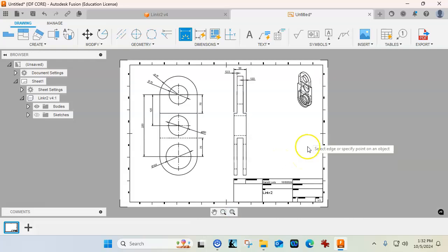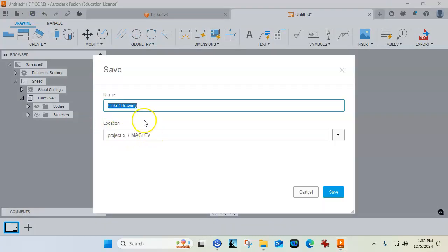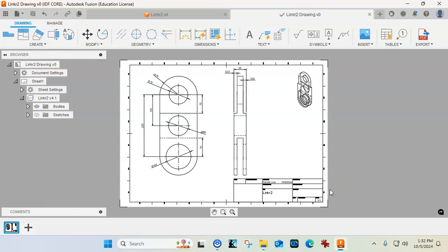F6 to fit it to the sheet, and then we would save this, and now we have a working document we print to. If I created my own template, I prefer to go across the bottom, clean that up. Not exactly sure what size I picked either, so this looks like a pretty good size sheet anyway. So we'll go ahead and save that and make it into a document drawing that we can come back to and clean up a little bit more later.